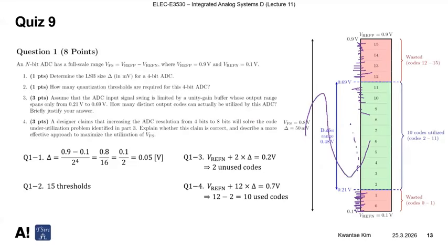No matter how good the resolution is, we cannot use this area because our input swing is still very small. That is the reason why increasing bit resolution does not solve the underutilization issue. The answer is if you increase reference N to a higher value and decrease reference P to a lower value, then you can make better use of the input signal swing. That's the reason why we use reference P and reference N as we studied in the last lecture.